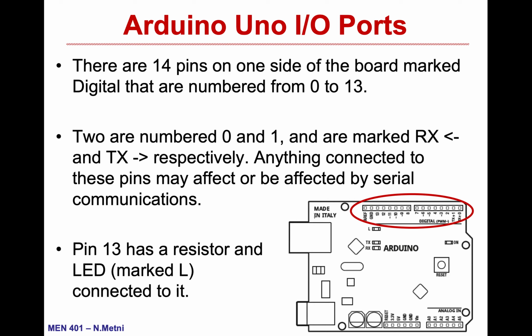This is very important for testing. I do not need to connect any external wires or a resistance to an LED to test something. If I want to test something, I will write HIGH on 13 and the LED will go on. There is an internal resistor and internal connection between 13 and the LED which is on the board.